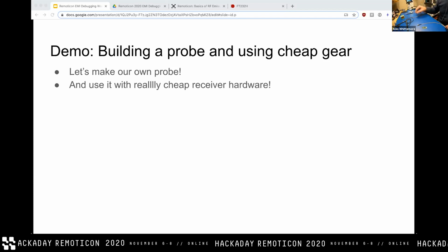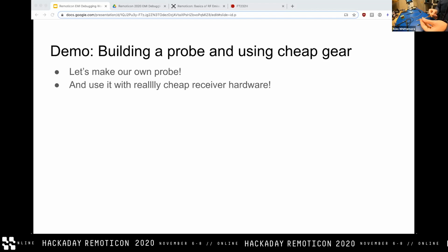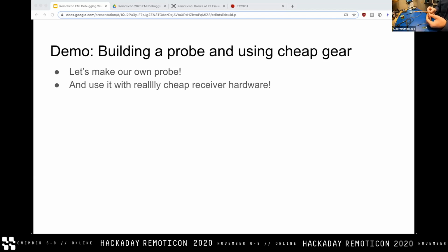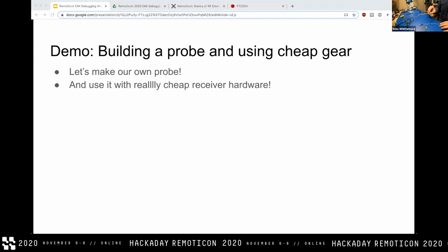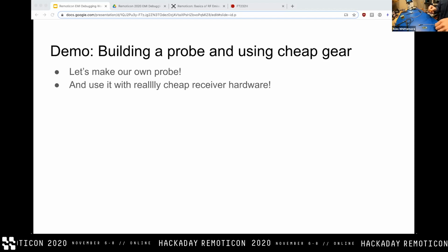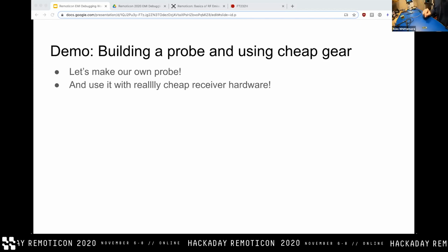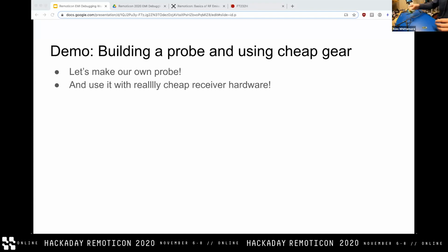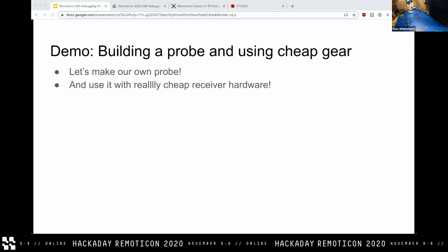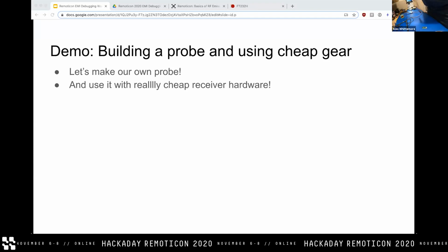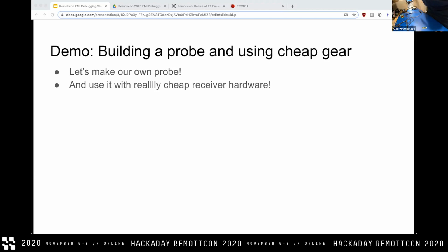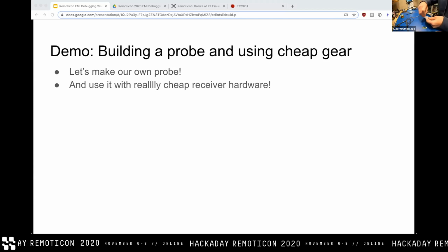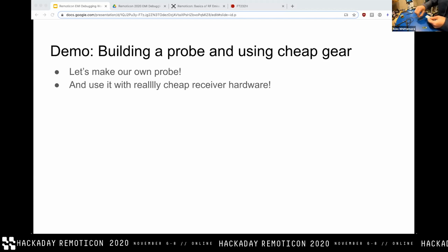So the way I made this probe, obviously it's magnet wire capped on tape and an SMA connector just taped onto a regular garden variety wooden skewer. I've got my magnet wire here. What I did was, I hope I have this pin here still. Oh, I originally wound this on a pin, but we'll just grab some sewing needles out of my thing instead.